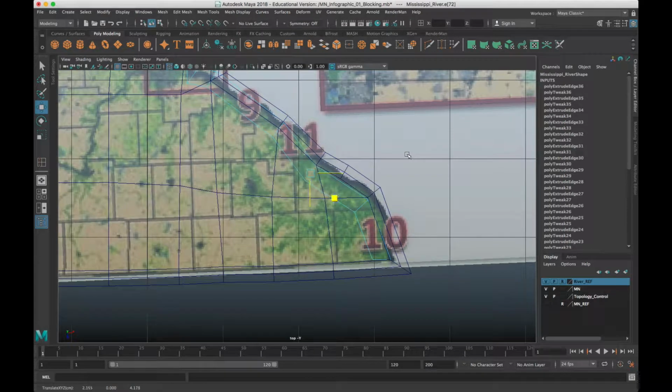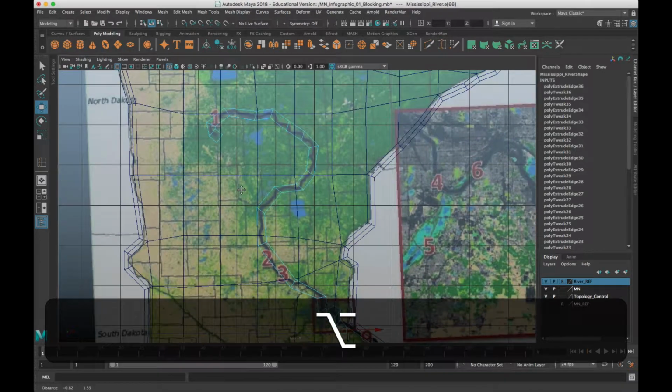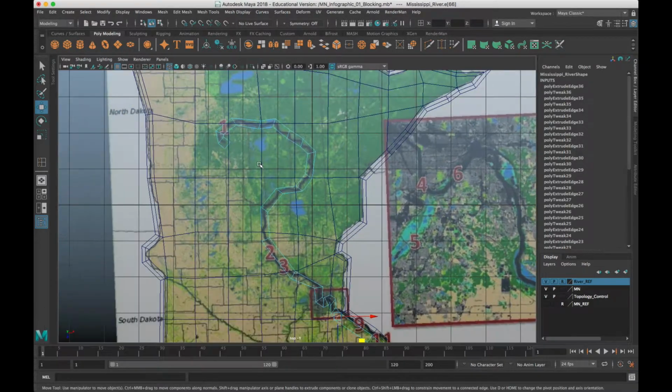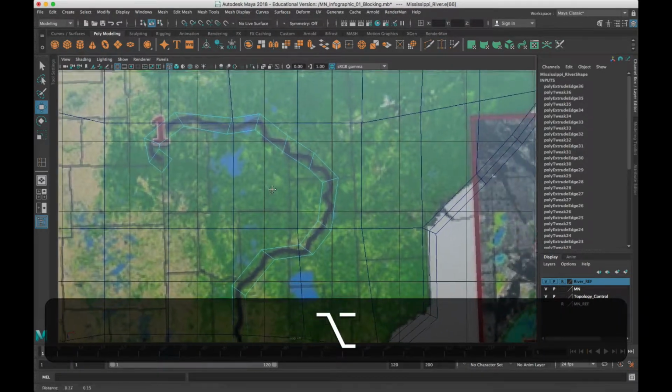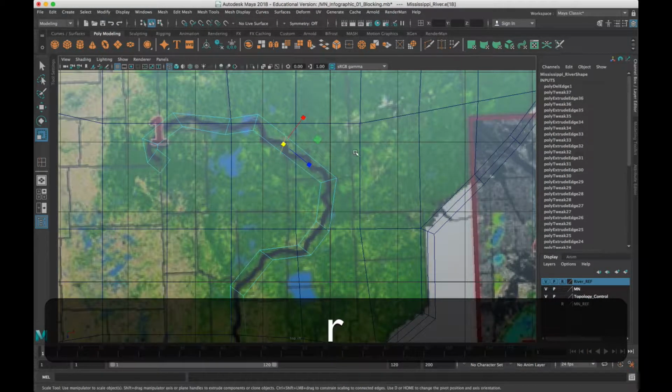All right, I'll just kind of move them. And then I'm going to go back and just look at each of the cross sections here, and figure out if I've got more than I really need. So right in here, I don't think I need 2 edge loops. So I'll select one and just Control Delete. And really, well, I'll keep that one.